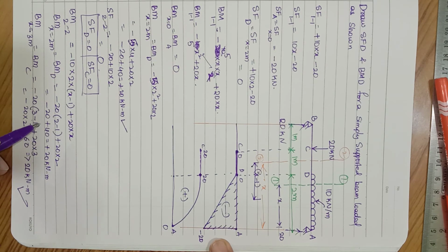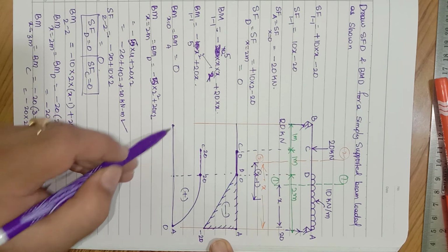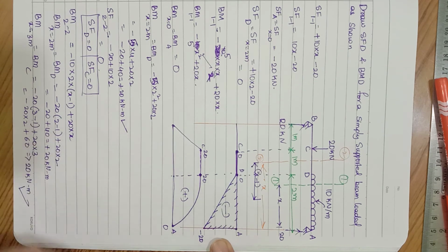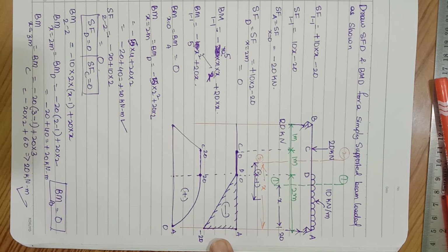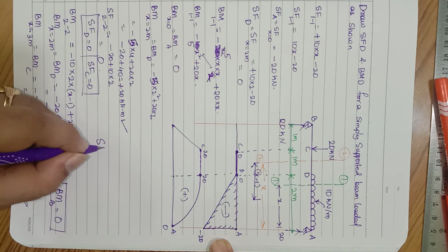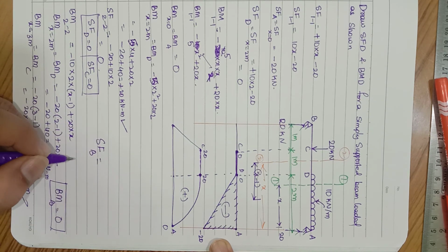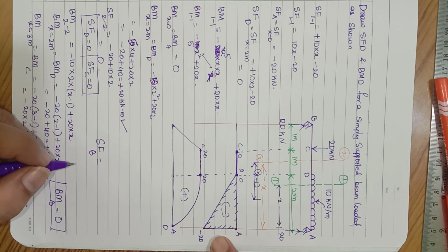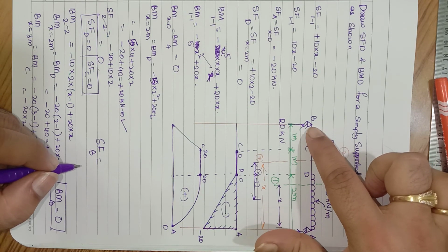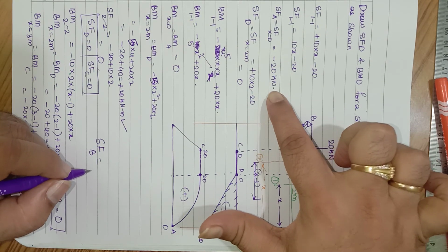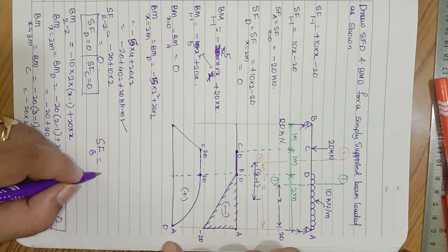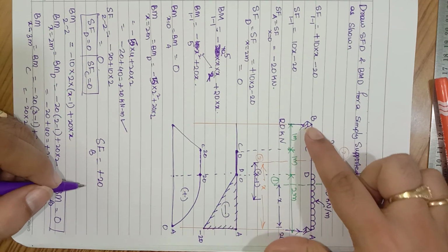And there is no need to calculate the bending moment at point B, right? Obviously you can directly join the line, because bending moment at point B for a simply supported beam, at the end, will be equal to 0. And shear force at point B, there is a small note which I gave you in the previous classes, that at point B where there is support, shear force will be equal to the support reaction. And shear force at A is 20 and shear force at B will be equal to plus 20. So this one is negative, this one should be positive.